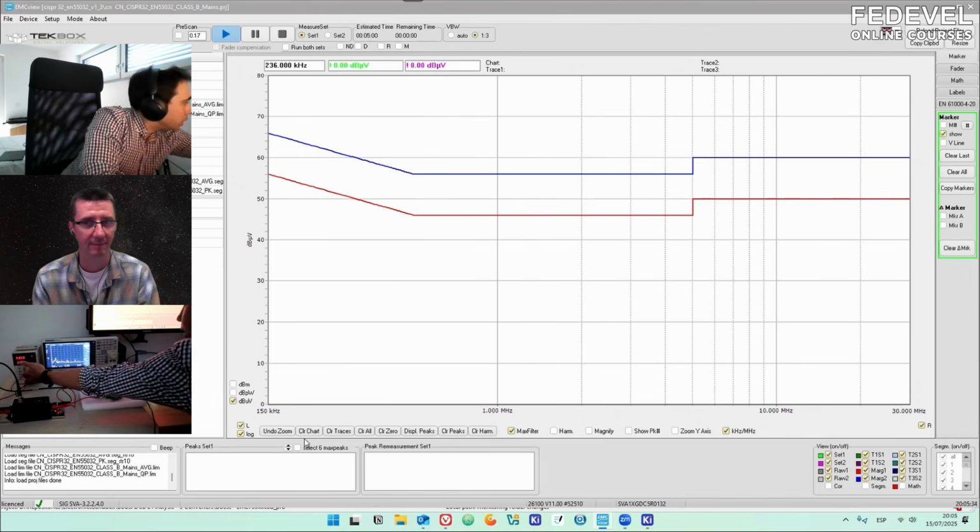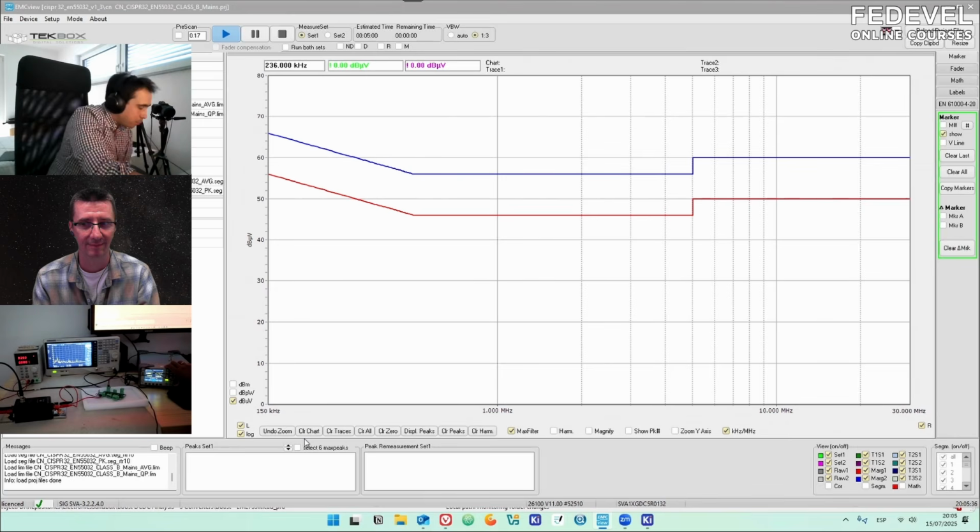So I connect the power supply. I see here 5 volts. I add a load. Let's make it interesting. So let's see, 1 amp can be too much for this power supply. Let's say 800 milliamps, which is already quite a bit of load. On the spectrum analyzer, we see that there are things moving, but we are going to make the measurement here directly because it's not the same.